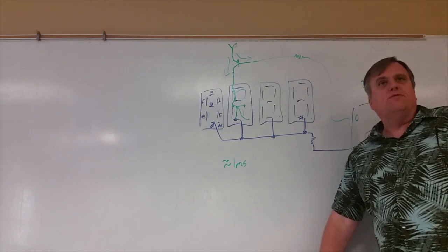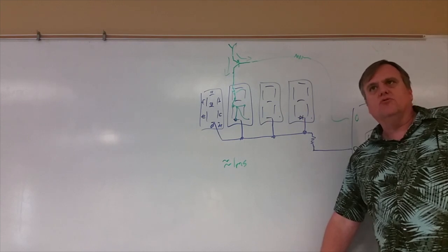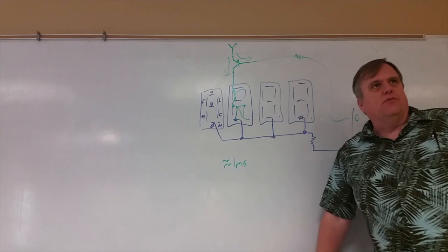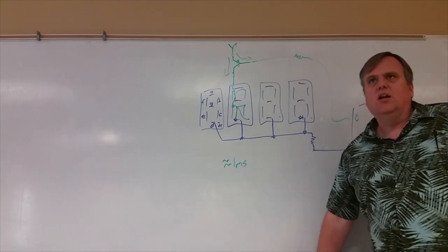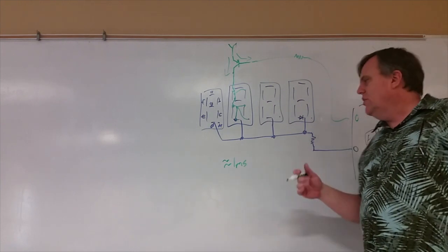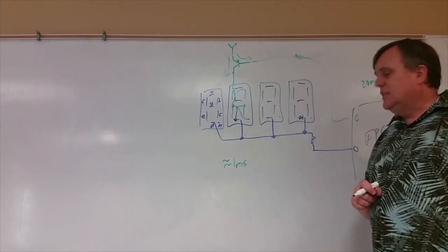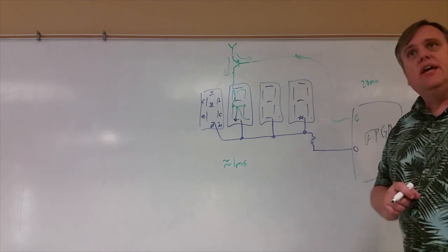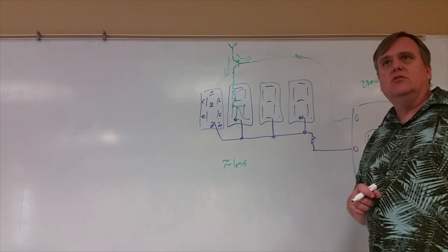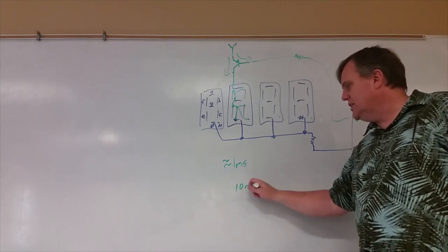But a lot of FPGAs are anywhere from 20 to 100 megahertz. It's pretty standard ranges. You just look at the clock timing number on them. I believe ours is 100. You just look it up in the spec sheet and away you go. But we want to get to the millisecond range. So if I'm at 100 megahertz, how long is a clock cycle? 1 over 100 megahertz, which is about 10 nanoseconds.